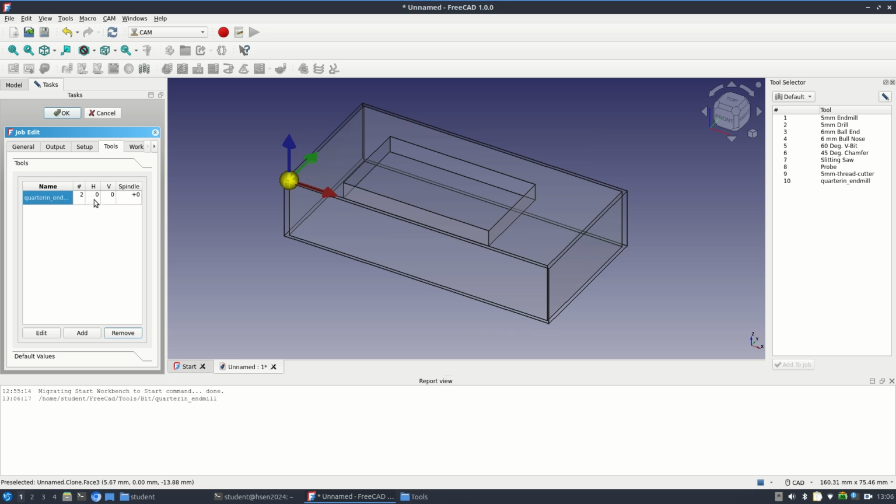Okay. So what I want to do is I want to change the feed rates for our tool as it moves in the CNC program. So the horizontal feed, let's say it's going to be 700, and the vertical feed is going to be, let's say, 800, and the spindle speed is going to say 8,000, right?